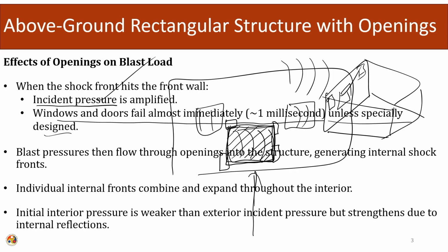So, joints are the most critical component when we are dealing with any sort of openings. When we are dealing with doors, when we are dealing with windows, not only the configuration of this plate from which the door or the window is made, the configuration of the joints is very critical. Why? Because in a very small area, the cross sectional area of the joints, whether they are acting in shear, whether they are acting in bearing, will be very small. So, in that small cross sectional area, the entire thrust of the blast load transmitted to the window or the door has to be sustained.